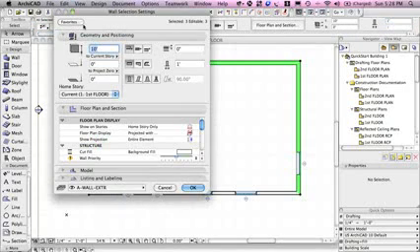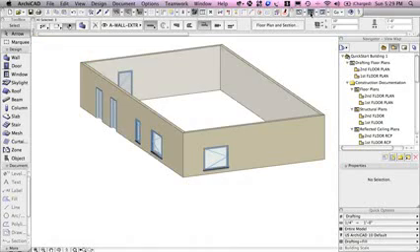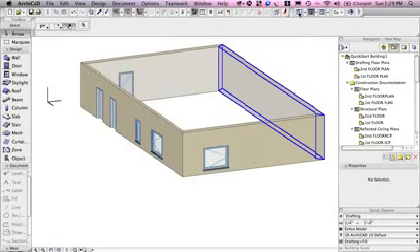or potentially when I open up the wall settings by clicking on the wall icon, I can change it here. Let me just make it even thicker just so we see the change very obviously on plan. Now I can change other things. I can make its height or materials or other things different, but for now this is going to be the most obvious that we can see. Now if I go to 3D, we'll see that instantly these walls are also changed in 3D.